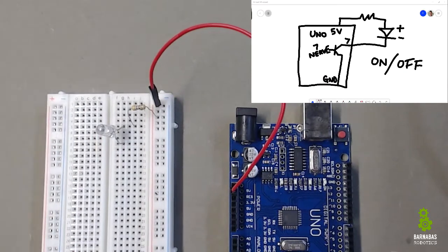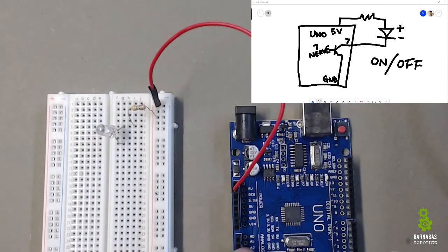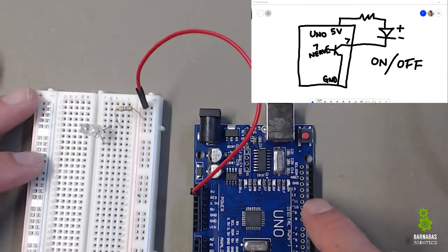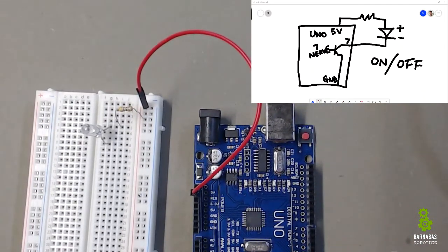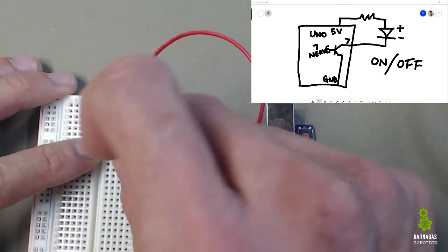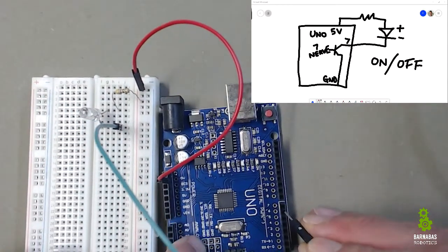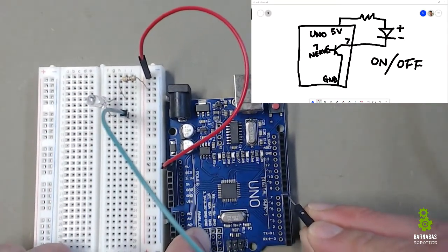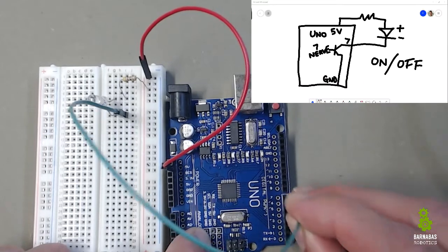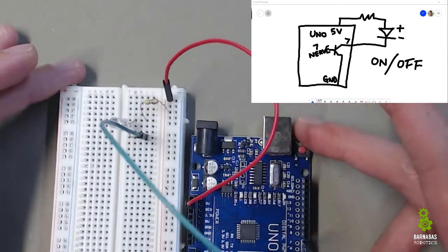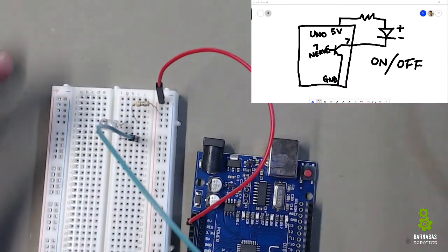And then let's not use black, because now we're connecting it to actually a transistor here. So let's use green. Let's go to the minus row, which is row 8 for me, and go to pin number 7. Pin number 7 over here. Boom.